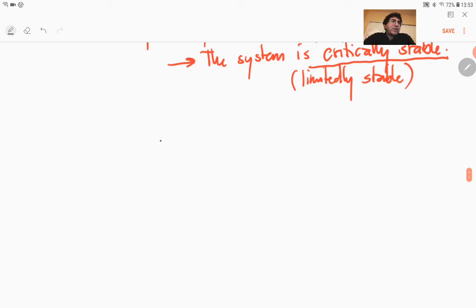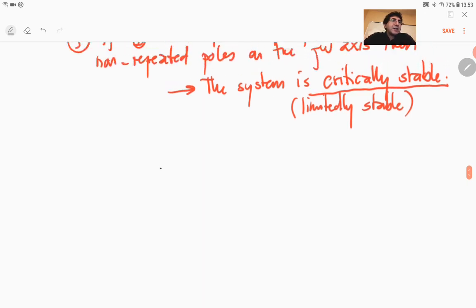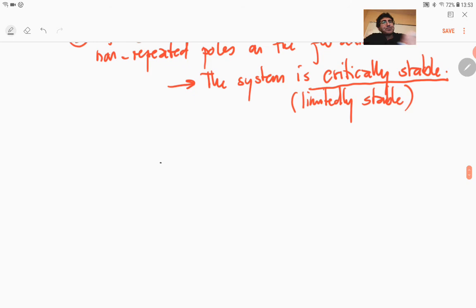But you need to find out the response, for example, a step response of the system by using, again, a MATLAB tool like the step function in order to find out what's going to be the output. So the tools that we will learn in the coming lectures will give us pen and paper type of tools to talk about stability, but they will not give us tools to find out about the exact performance parameters of the system.